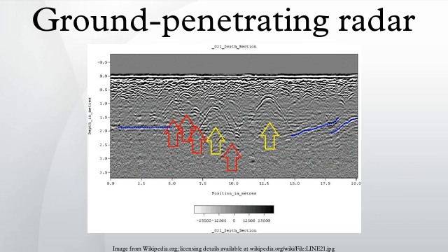Other disadvantages of currently available GPR systems include: interpretation of radargrams is generally non-intuitive to the novice. Considerable expertise is necessary to effectively design, conduct, and interpret GPR surveys. Relatively high energy consumption can be problematic for extensive field surveys. Recent advances in GPR hardware and software have done much to ameliorate these disadvantages, and further improvement can be expected with ongoing development.